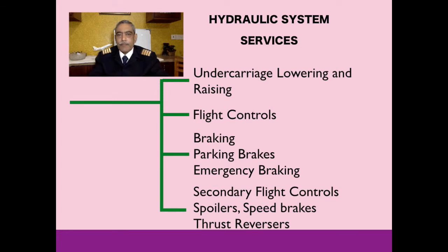And the aircraft braking also uses hydraulic pressure, which also requires a fairly high degree of power, and the parking brake and the emergency braking. And of course, almost all the secondary flight controls such as speed brakes, the spoilers, and the thrust reversers, almost all movable controls are operated by hydraulic systems.